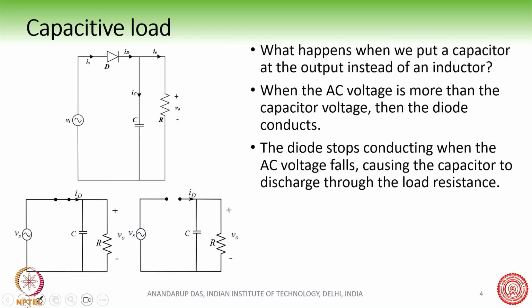The idea is that if you put a capacitor instead of an inductor, then when the AC voltage is more than the capacitor voltage, the diode will conduct. Ideally the diode is a short circuit.